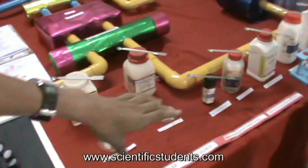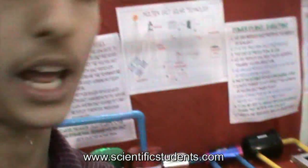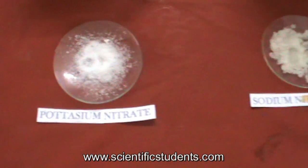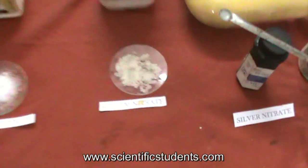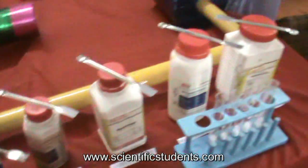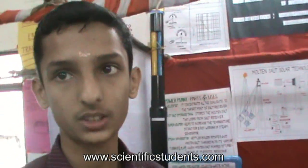We are going through research to find various salts that are most suitable for our power plant. Then we think that the mixture of potassium nitrate and sodium nitrate is much more available. For planting our power plant, we want more availability of these salts. We also considered nitrate salts like lead nitrate, barium nitrate, magnesium nitrate, and ammonium nitrate. When we pass these salts through the jet tube, some of them are blocked inside, so our power function will be blocked. So we selected sodium nitrate and potassium nitrate as our storage medium in this power plant.